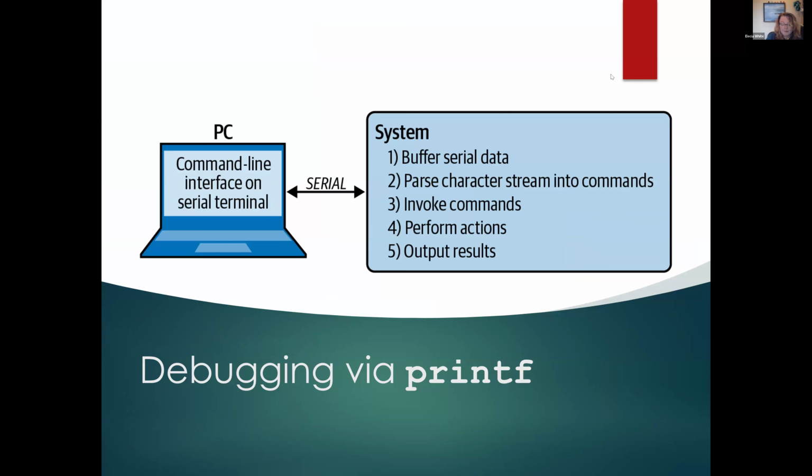However, as an embedded system often has to do things quickly or react to an input in a very small but specified amount of time, which is called real time, printf can cause problems by changing the timing of the system. Kind of like the uncertainty principle, Heisenberg. You can't always run what you want and be able to see what you're running at the same time. See previous mention about debugging being like playing Tetris. And I say printf, but what I mean is output through a serial port. Serial ports are common in embedded systems because they are so very cheap to add to the hardware.